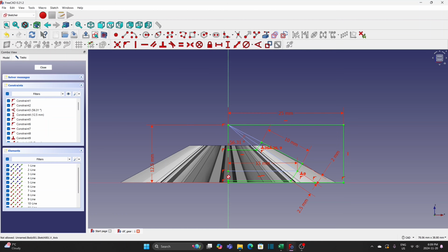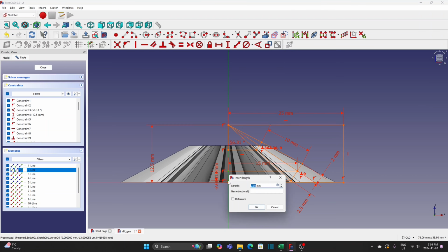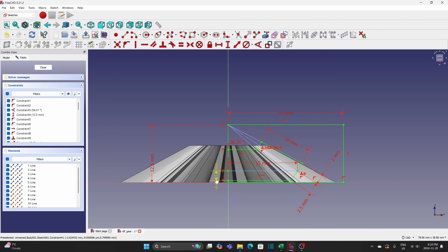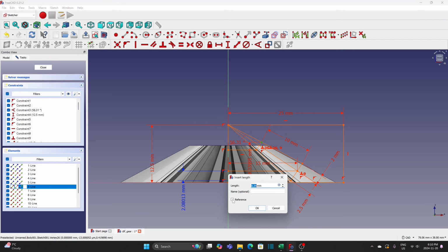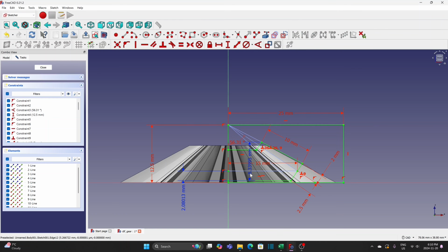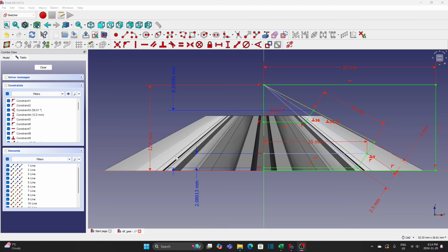Check the offset distance, which is from the pitch circle to the base of the gear, where I will create a LCS. It is 2.08 mm. The height of the gear is 8.34 mm, which is what we need. Part of the shape is outside the primitive gear.